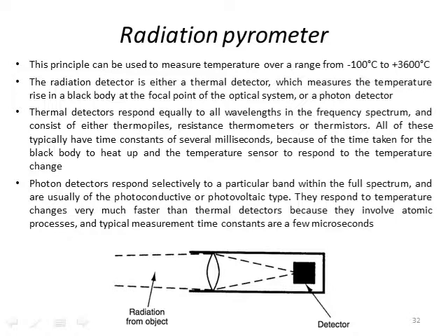So when you have a certain radiation, it generates current, just like a photodiode. But these are calibrated and work within the far infrared region. The radiation will be focused with a particular type of infrared lens, and then the radiation comes in, and you have an electrical configuration that detects either a photoconductive or a photovoltaic type of detector.